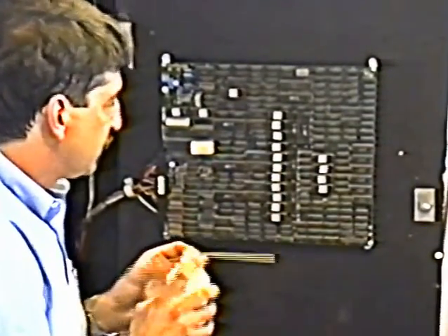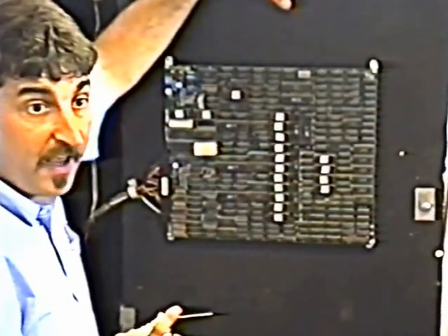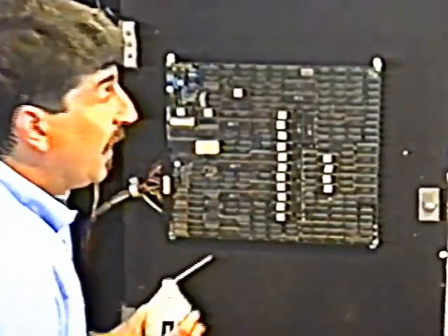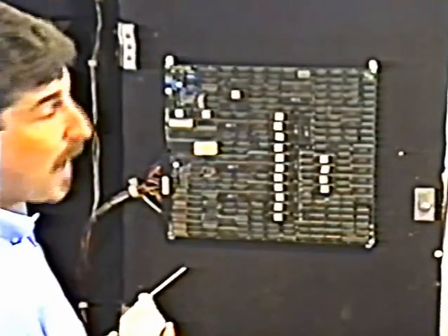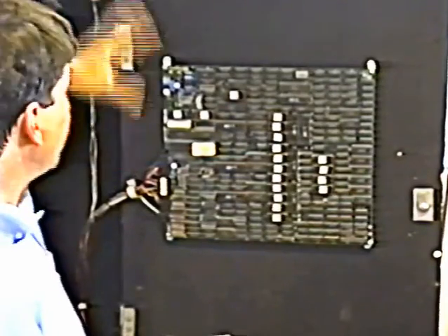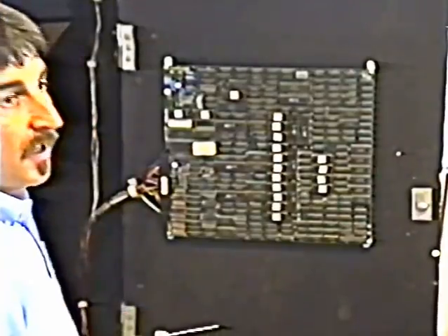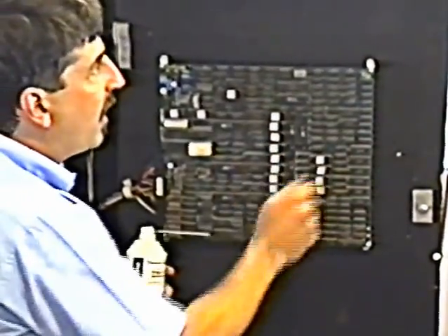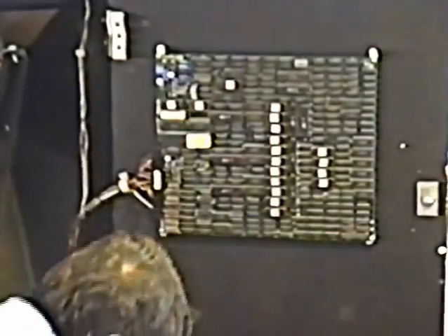And what you do is this. First thing you do is you have to heat the board up so that you actually have the failure. You have to actually have the failure, obviously, first before you do this. There are several ways to do that. One way is to close the game up, tape up all the vent holes, and wait till it fails. Another way is to do that, but throw a light bulb inside, like a regular 100-watt light bulb. Best way is the hair dryer. Steal your old lady's hair dryer. Heat it all up with the hair dryer until the failure occurs.